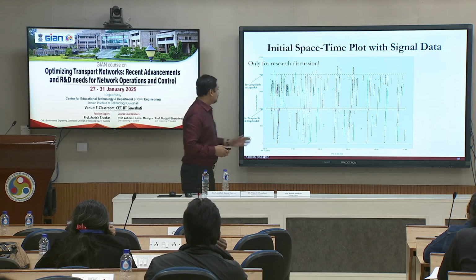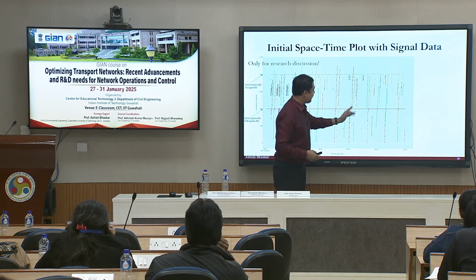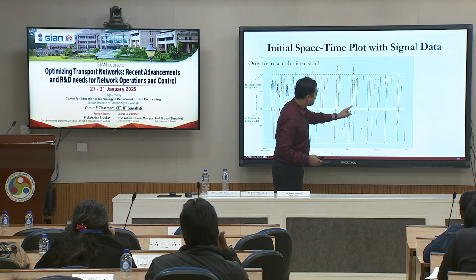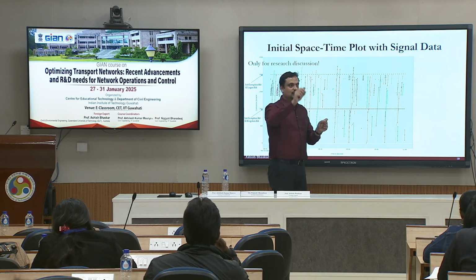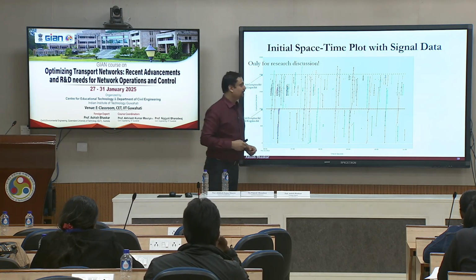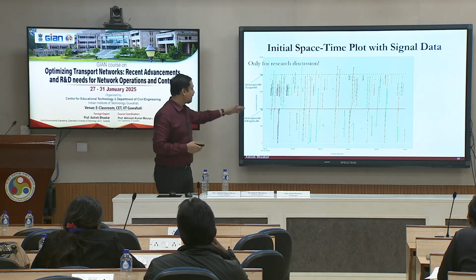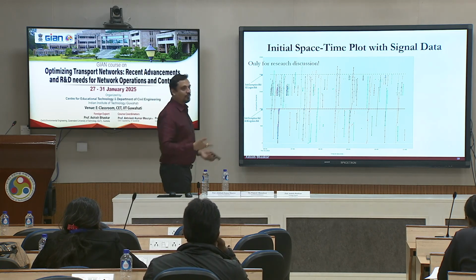Without stopping, good. Actually, it looks like they cross without stopping. For example, this one data point was here, other one was there. So you might have to look at the average speed. This one definitely crossed without stopping. This one might have stopped and then left, but because your one data observation was here, other one was there, you did not get the actual stop and go condition. So you can find the delay easily to a certain extent along that intersection. You would have got more information, yeah.